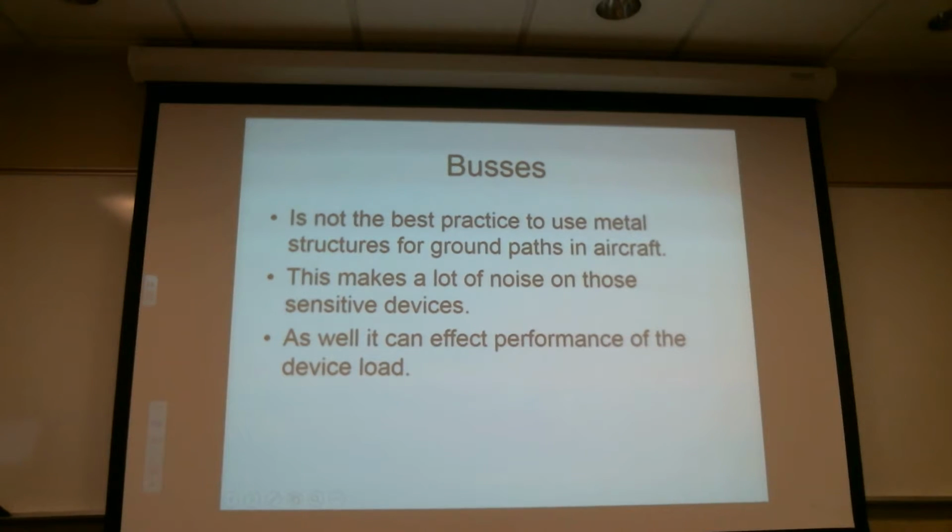Huh? They're not anything to do with each other. Well, the one thing they had to do with each other was the ground. The ground was a weak link because of the way this connector went together. I had to stare at that schematic for a long, long time to figure out how ground was finding it. It kept looking like it was finding its way through the headlight. It wasn't. It was finding its way through the coil, the activation coil of the high beam relay.